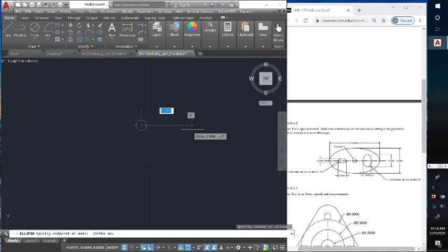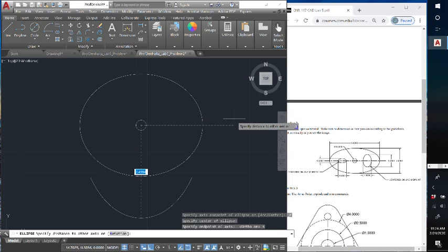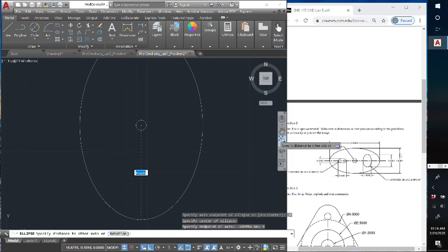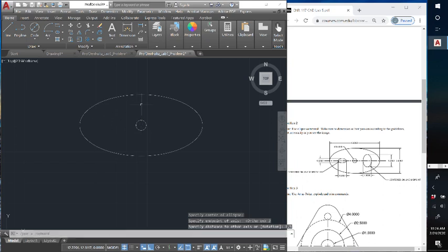What we're doing right now is defining the horizontal distance from the center to the edge. We can see that it's 6 all the way across for the large ellipse. Horizontally, it's 6 across, so from the center to the edge it would be half that, 3. So I'm going to type in 3. And then same thing here. We could see that vertically it's 3 from the lowest part to the highest part, and I want to go from the center to the edge, so I'm going to use half of 3, which is 1.5. And so that is our larger ellipse.